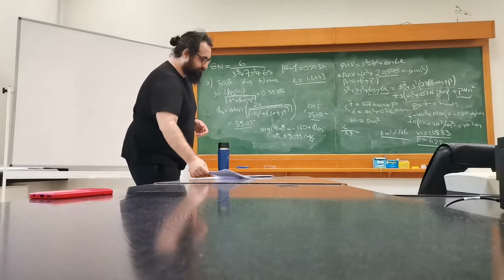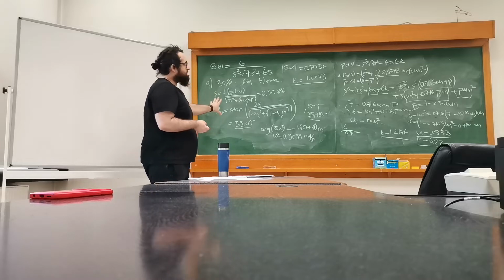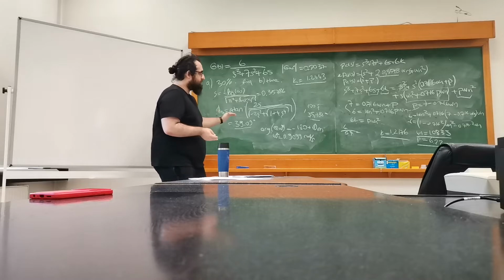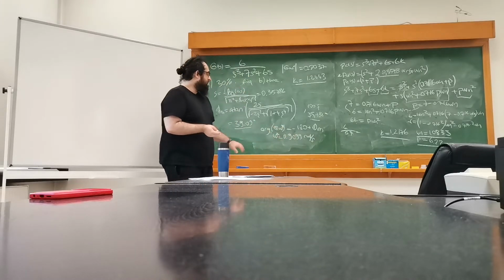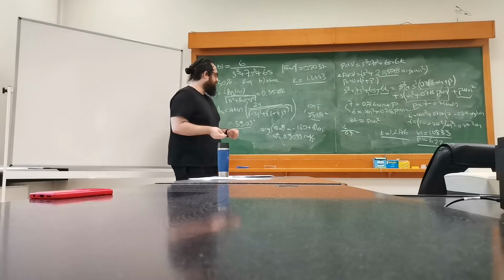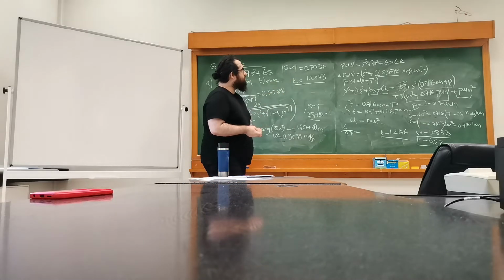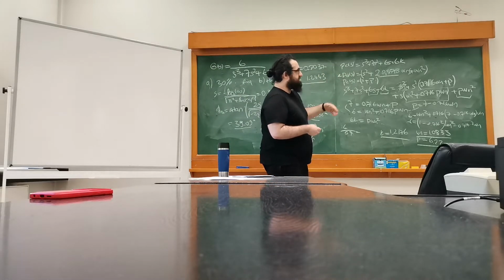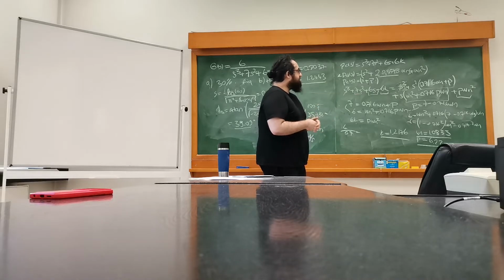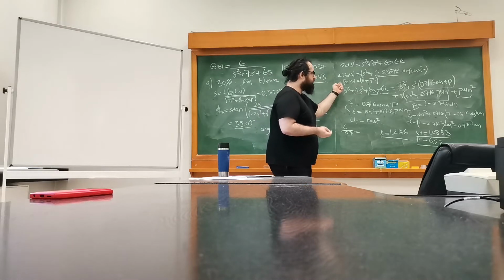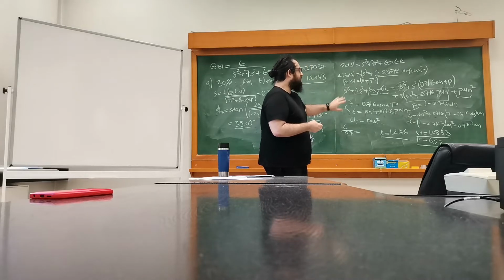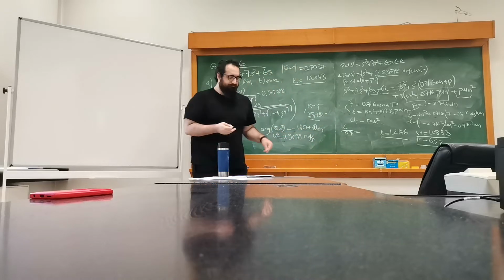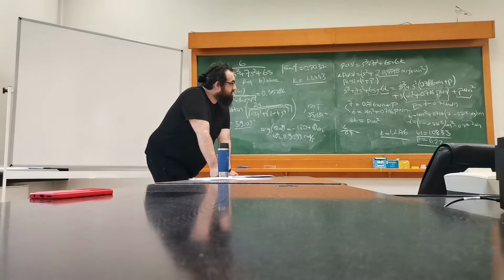You can see now that this here is basically very standard. You have an algorithm here: look for zeta, look for the phi m value, add it to minus 180 degrees, look it up for the angle condition from the phase graph, come up with frequency, look for the gain value, take the inverse, and you're done. Here we have more modeling involved. You have to look for a desired polynomial. If your system is a higher order system, you have to add a residue pole to it. And then you have this algebraic method, just calculate everything, it takes more time. But you can evaluate your solution and see if it's really working, if it's a good one or not.